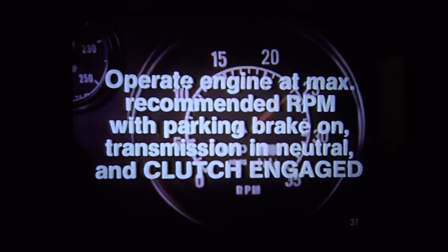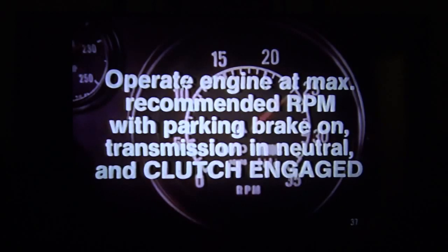If there is no vibration with the transmission in neutral and the clutch disengaged, slowly release the clutch and raise the engine RPM to its maximum recommended speed. If a vibration is detected, the problem is in the clutch disc or transmission. Remove each component in order and test to isolate the cause of the problem.